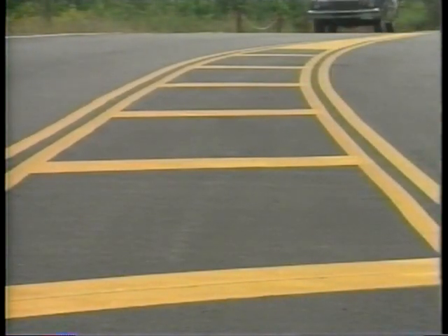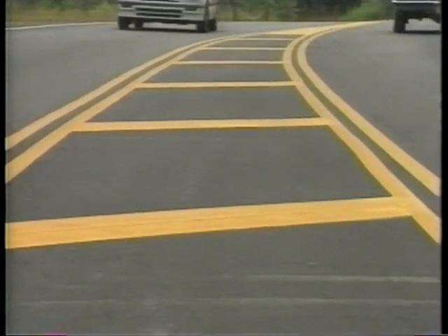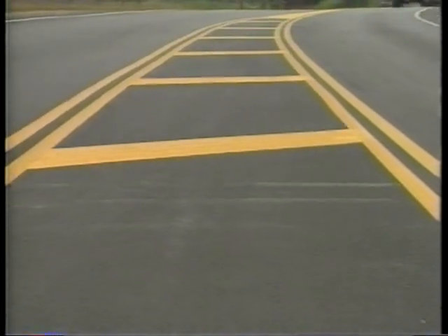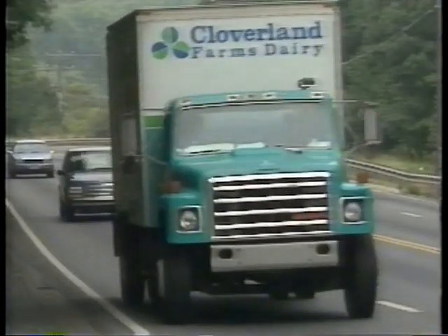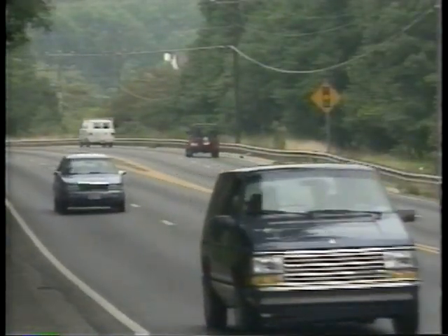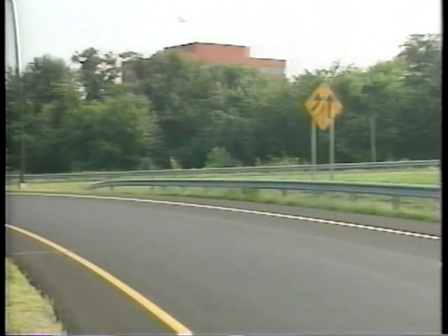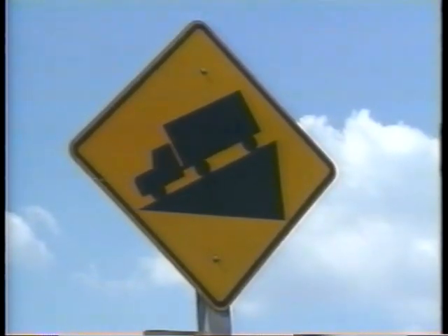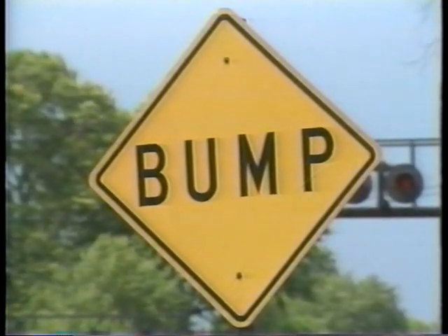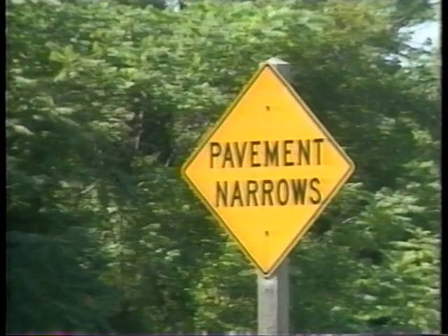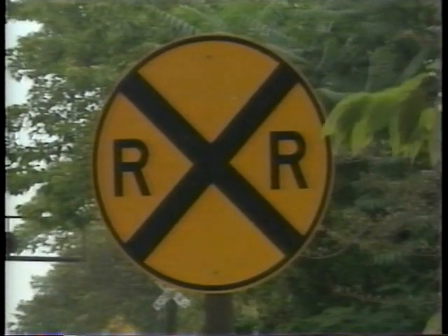Common locations of warning signs include abrupt changes in horizontal alignment requiring drivers to reduce their speed, ahead of intersections, in advance of control devices like signals, before converging traffic lanes, prior to grades, in advance of roadway surface irregularities, before narrow roadways, and ahead of entrances and crossings.